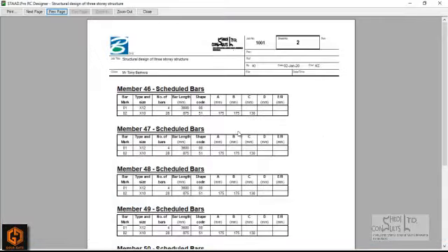So this is the requirement. Now, you see, he prepares the bar bending schedule. For bar mark 01, the member size is T12. You need 4 members of that. The bar length is 3.6.